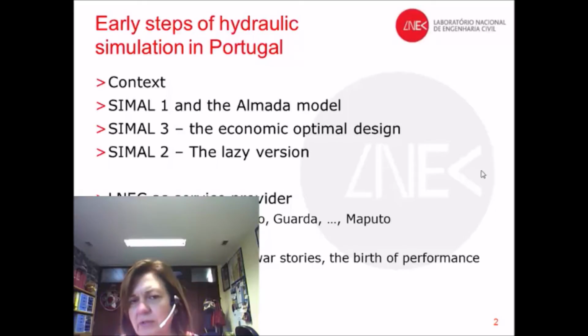Now, during the thesis, I worked a little bit on this and tried to understand, and now it's obvious. If the solution 0 is all equal diameters for the whole network, the hydraulic balance will lead to a distribution that corresponds to a minimum energy solution.